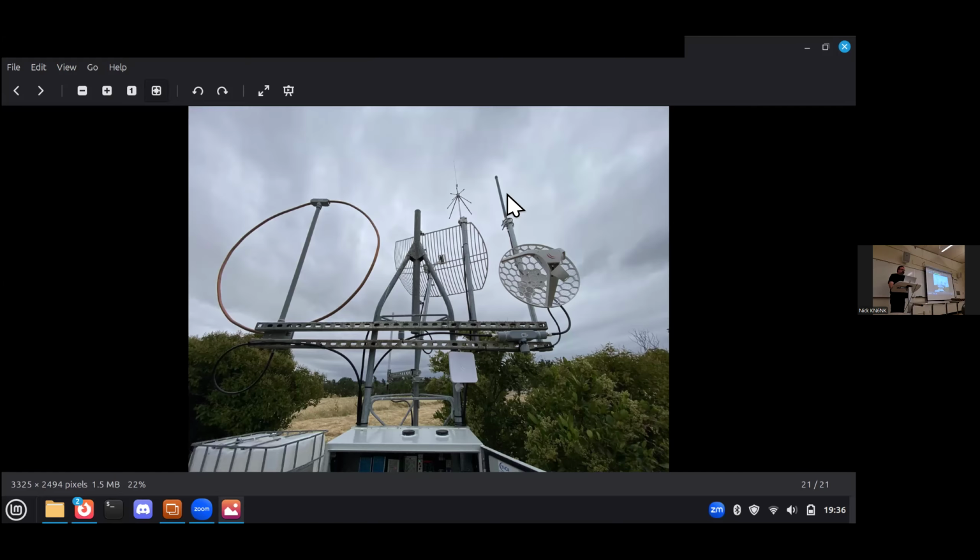Is there not anything like that for this purpose, for dividing the signal? Yeah, the multi-coupler. The ones that I had were one in, antenna comes in and then you have 4 ports out. And if I had added the ADS-B receive to that, I would have had more than 4 things.